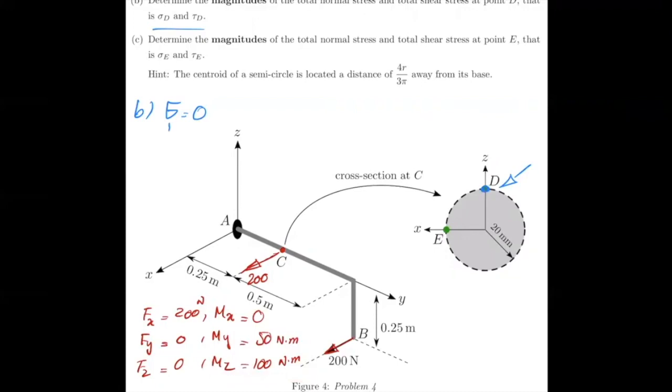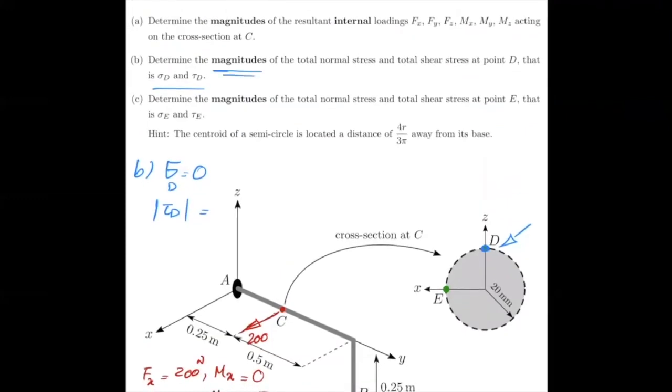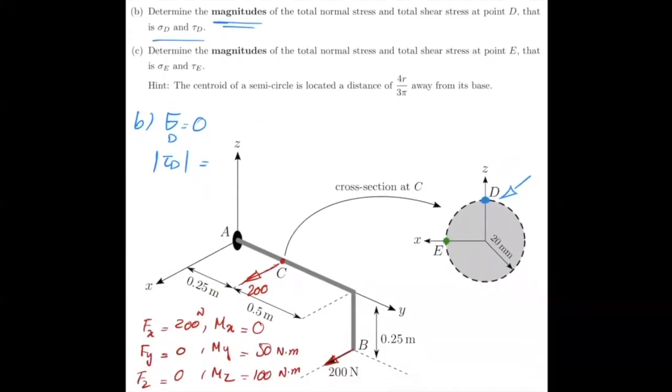Your shear stress is a combination of two types of stress. And then maybe I talk about its absolute value because it asks you for magnitudes. So it would be Tc over J, it's your torsion problem, minus VQ over It. And from the dimensions and the values that we have, we can calculate these and you would get 3.77. I'll explain that in a moment.